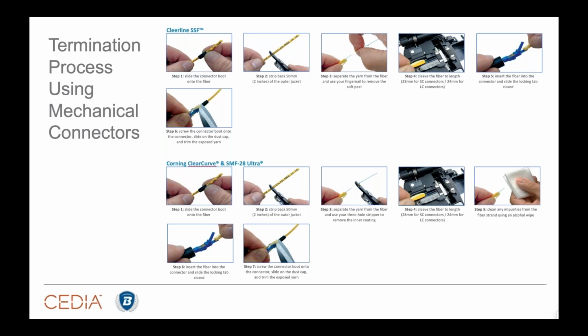However, the type of fiber optic cable you have will dictate different processes. What do I mean by that? There are really two types of optical cores inside the cable that you'll use. You will have polymer cables, polymer-based glass. It's really hard to fusion splice, and it's fairly specialized, but if you're using a mechanical connector, it's great. It terminates quickly and is incredibly robust cable. Literally, you can tie it in knots and it won't break. It's a good way to broach the termination topic.